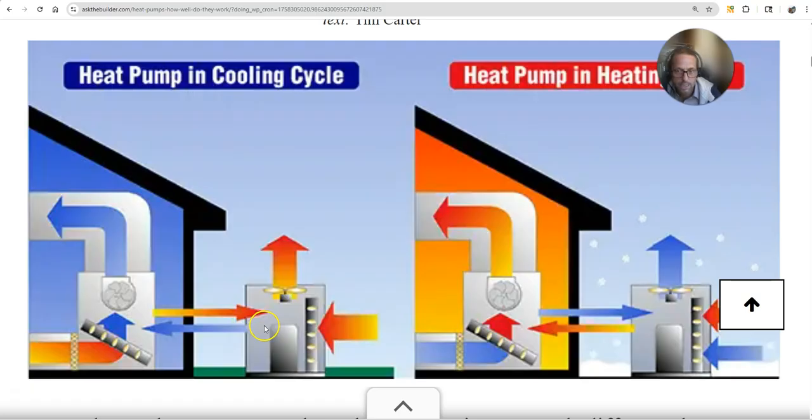That's all based on latent heat transfer, because the latent heat is where that energy is stored in that air. And what's great about a heat pump is they're reversible. So in the heating season, you actually do the opposite. You take heat from the outside air, and believe it or not, you can pull enough heat from outside air, depending on how cold it is.